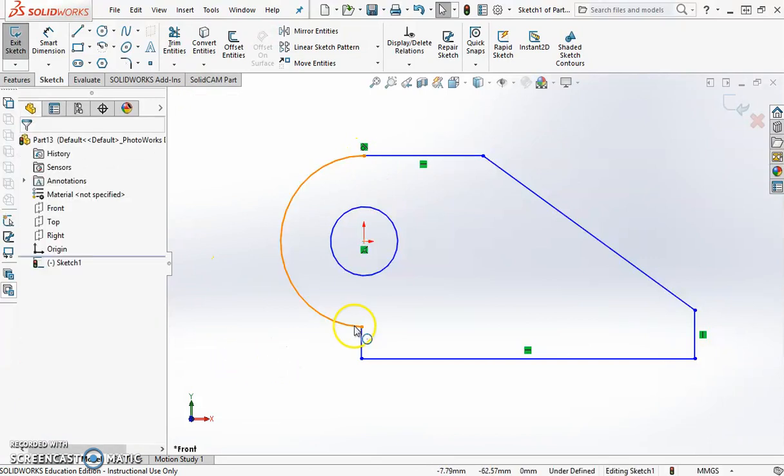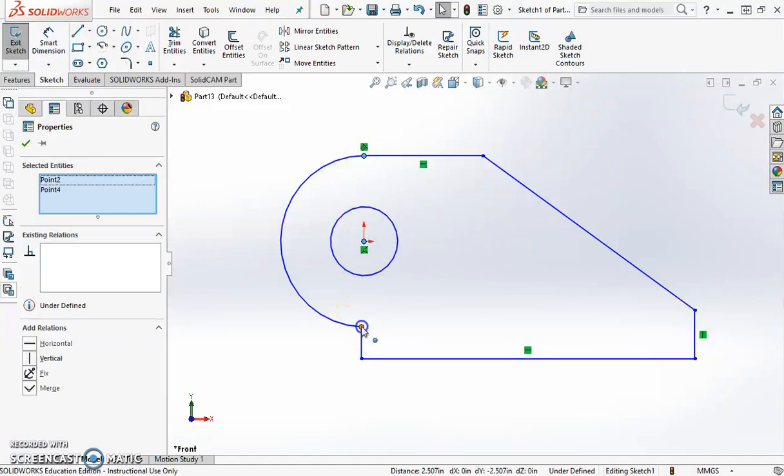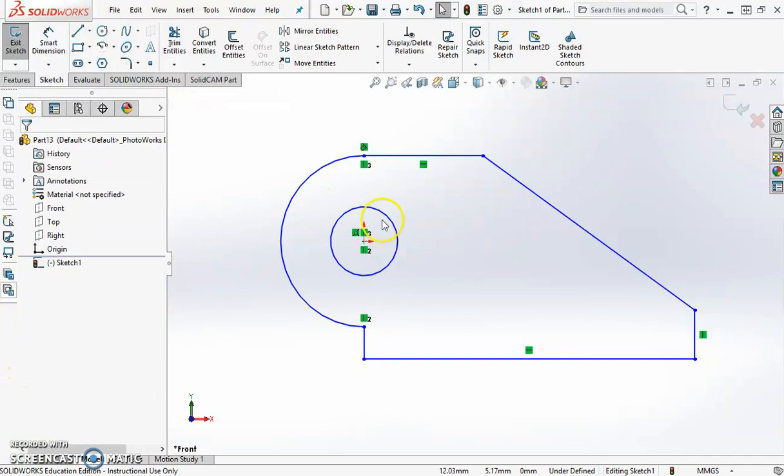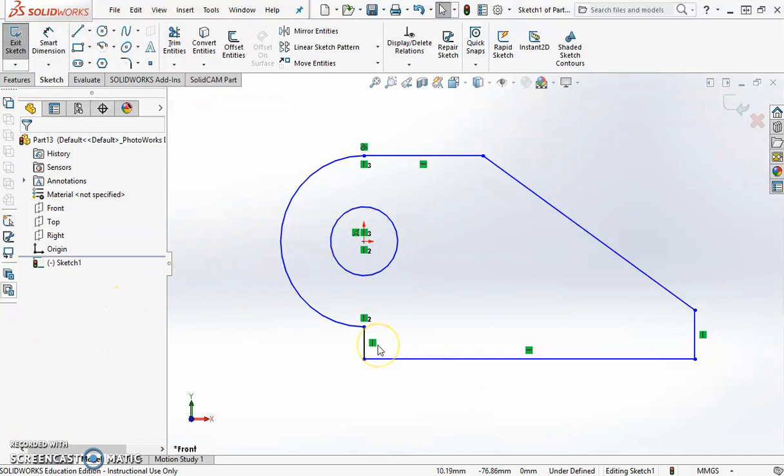And then down here at the bottom, we want to make this straight up from the origin, same thing with that. So let's click that dot up at the top, hold in shift, click your origin, and this dot down here, and let's make them vertical from one another. So they'll all line up. Okay. Now, if this line up at the top isn't horizontal and this line down here isn't horizontal, please make them. This line also has to be vertical, and so does this one. And I noticed this one is not on mine, so I need to make that vertical yet. There we go. It was on a slight angle.